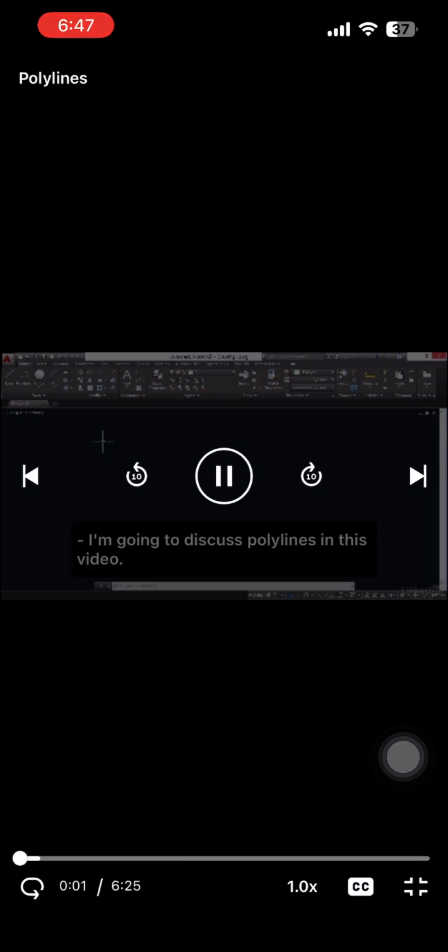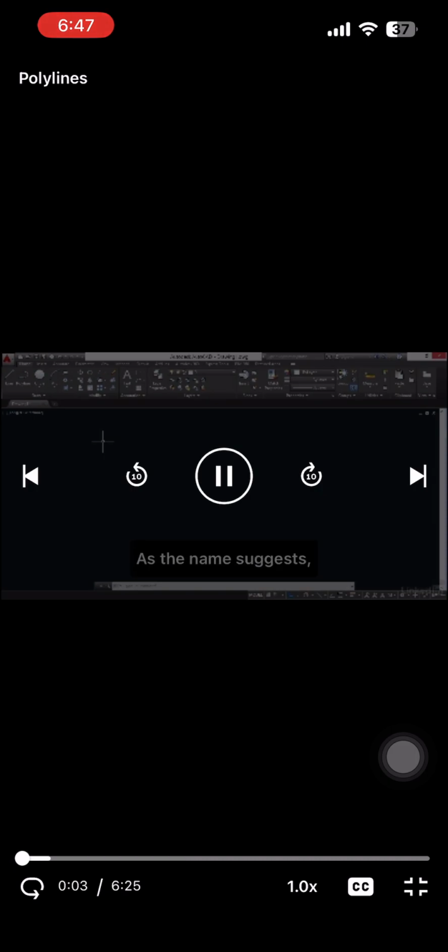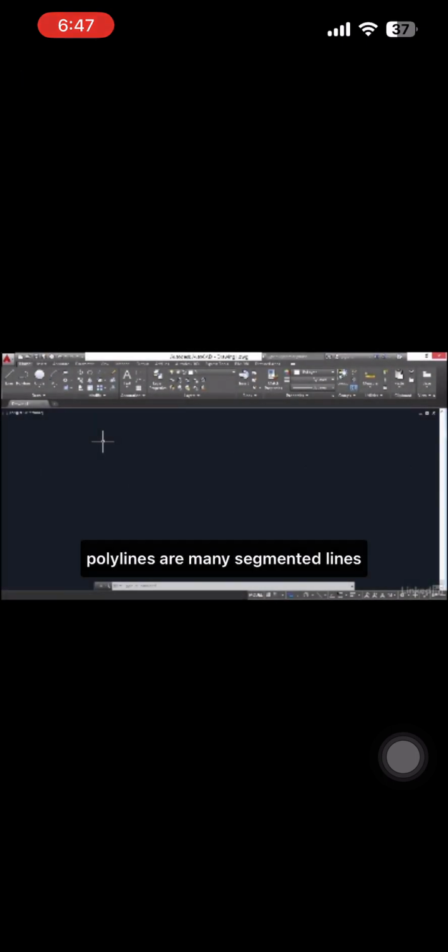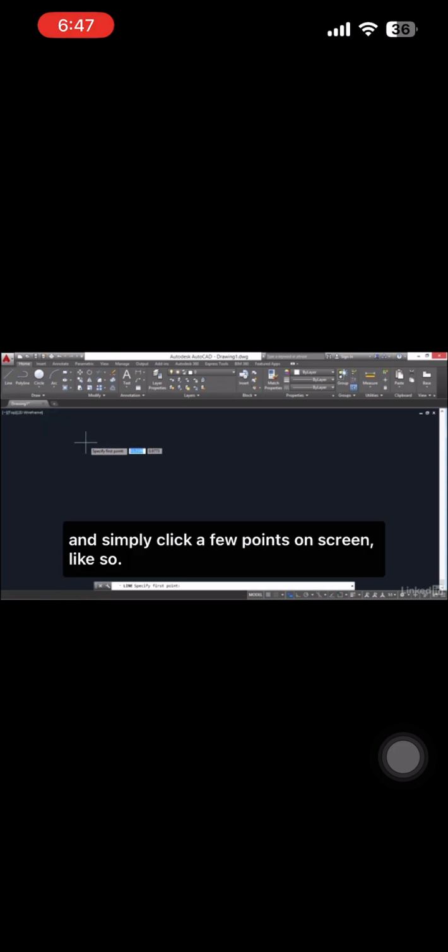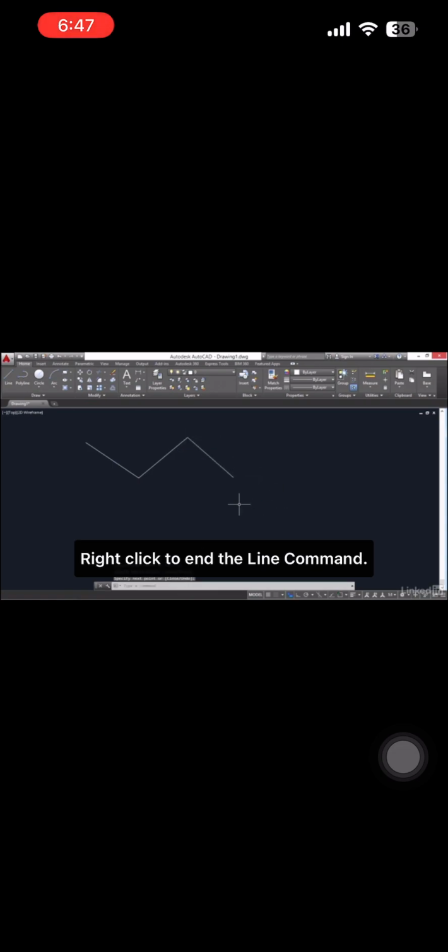I'm going to discuss polylines in this video. As the name suggests, polylines are many segmented lines that behave as single objects. Before we create a polyline, let's start by drawing a few line segments with the line command. Click line, and simply click a few points on screen, like so. Right-click to end the line command.